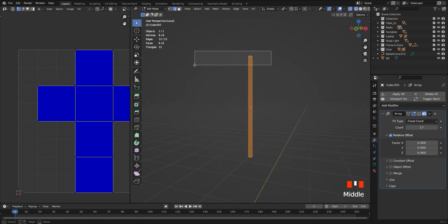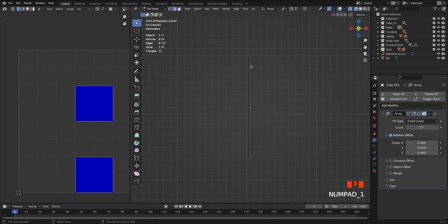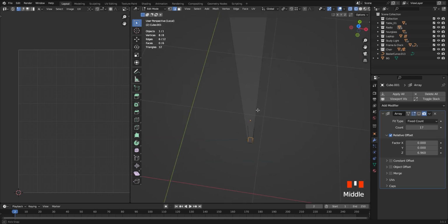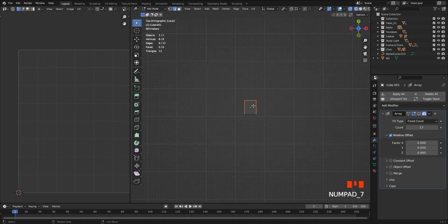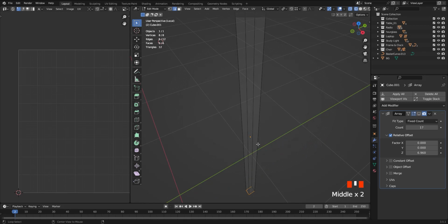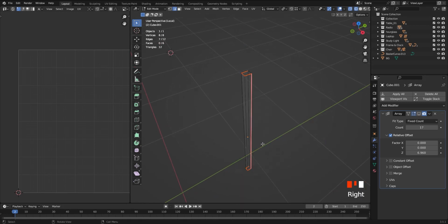Make a selection of the top and the bottom. Change your view angle. Hold down Ctrl. Deselect one edge. Better if it is located on the back. Press Alt-Shift. Connect them together afterwards. Mark and unwrap it.